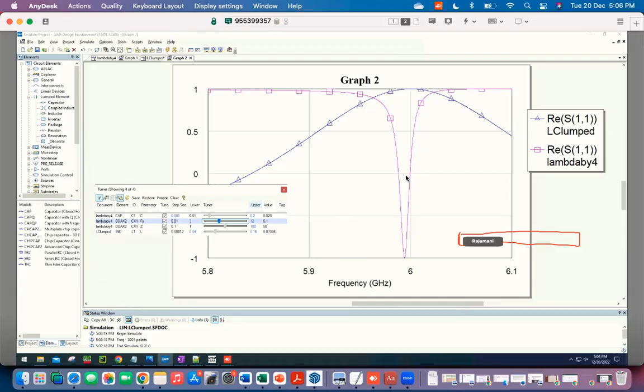And then I want to put a capacitance on this side between some incoming transmission line or my port. The way you would normally do it is that, if this microstrip is designed to be 50 ohms, then you just have another line and just put a small gap there. And the distance of this gap will determine how much capacitance you get.